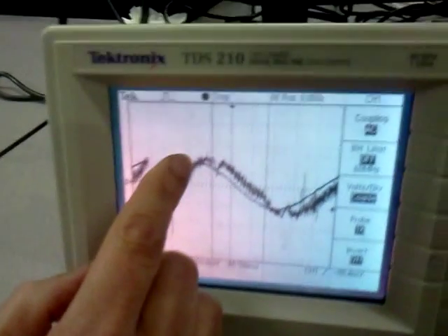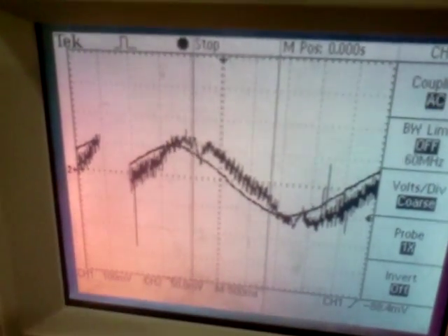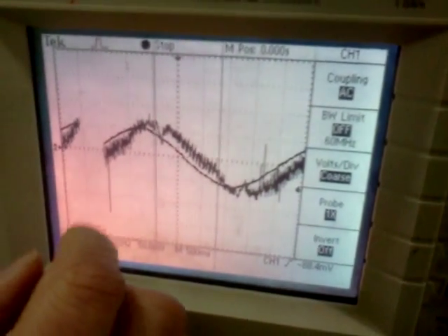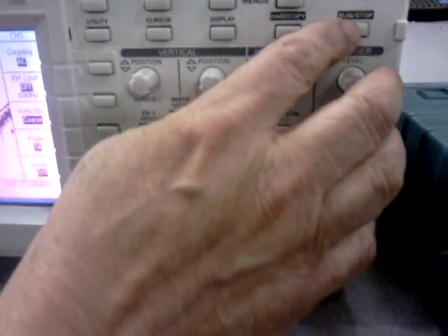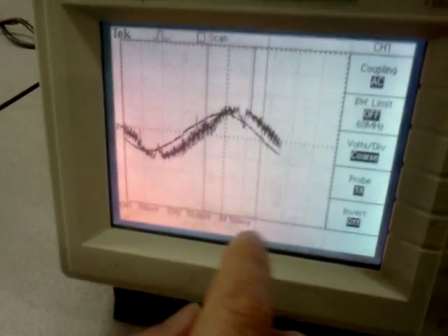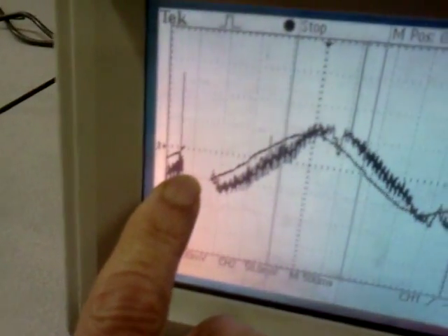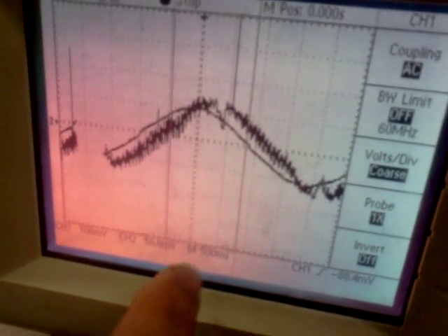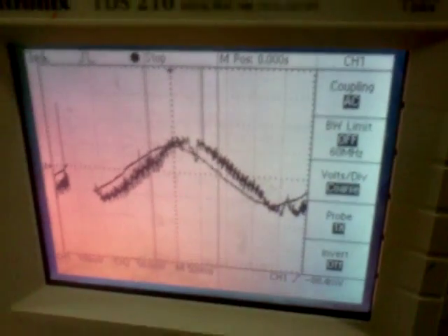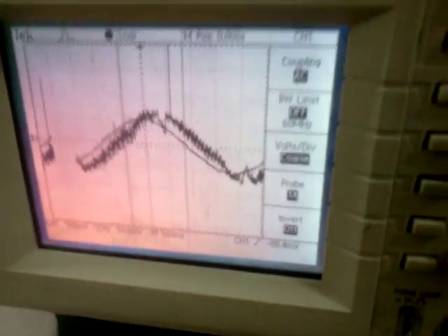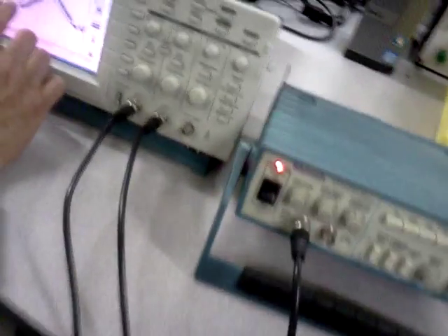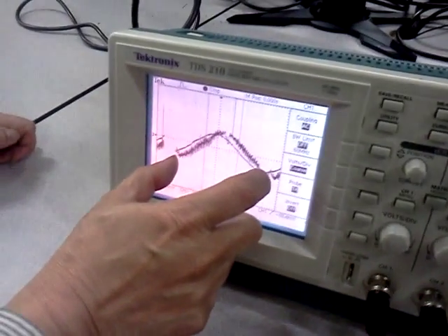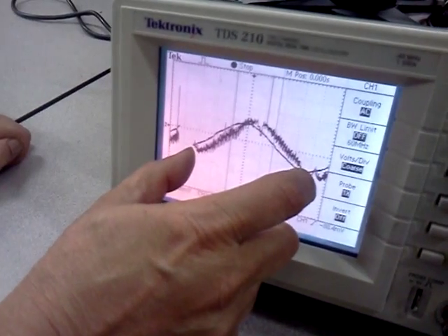So you can see here that from this peak of the input to the peak of the output is about 1 division. And since the period is much larger now, let's see the period. So you can see that the period is roughly 1, 2, 3, 4, 5, 6, 7. About 7 times 500 millisecond, about 3.5. So 7 divisions. So 1 in 7 division is the phase lag. So you would see that the angle is about 1/7 of one full wave, which is 1/7 times 360 or 1/7 times 2 pi radian.